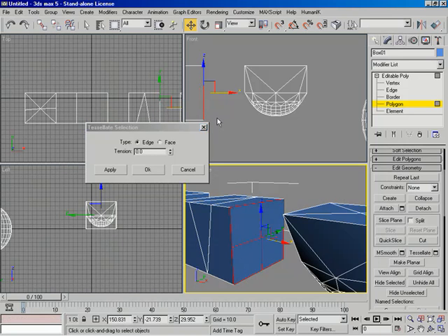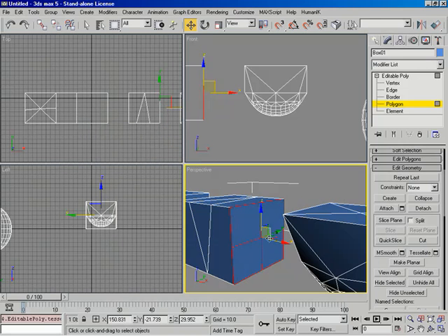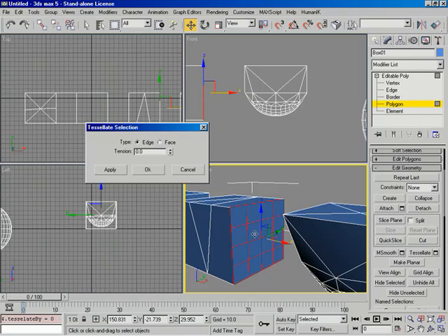So you have that ability to do right there. You could also just go in there and pull a vertex if you want. Yeah. So let's go ahead and hit OK, and we're just adding additional detail. Now if I come back in here and do tessellate again, since I have 4 different polygons selected, it's going to work on those 4 polygons.